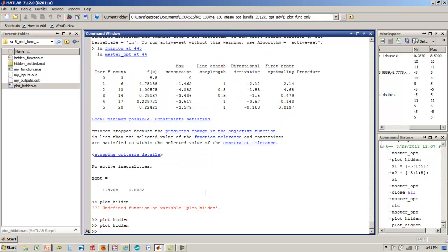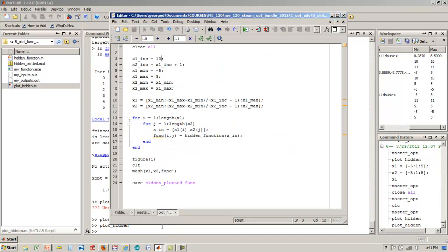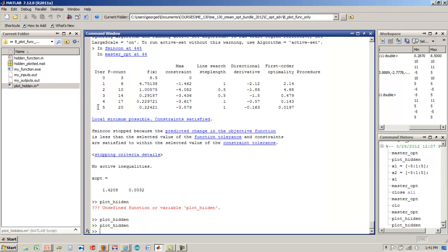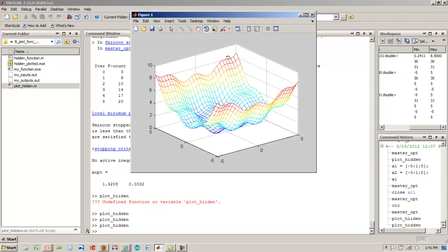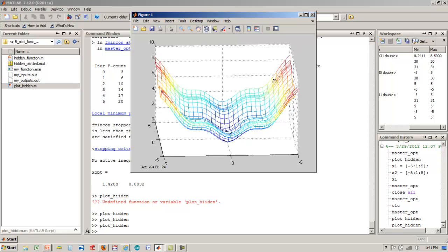And then you think to yourself, well, let me increase the mesh a little bit more to about 30 and see what happens. Run this again, and again it takes a lot longer to run, and many times you're better off just running the optimizer from many different starting points in order to gain information about the design space.